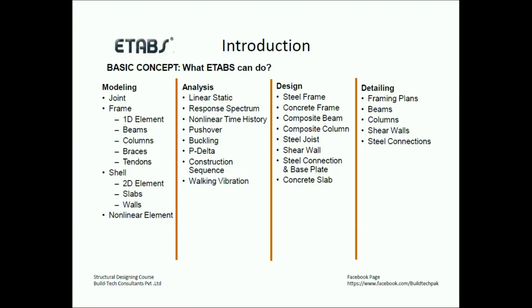The output of this analysis is basically the deformations, like you are able to see how much the nodes have been deformed due to certain load cases, and what the base reactions are. Like you have applied area loads on the structure, and ultimately you want to know how much the base reaction is. Once you need to design the footing, you need to know the values of the base reaction, like what reaction is coming under the columns. So after doing this analysis, you will be able to get all this information from your ETABS models.